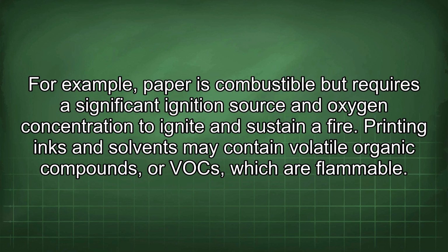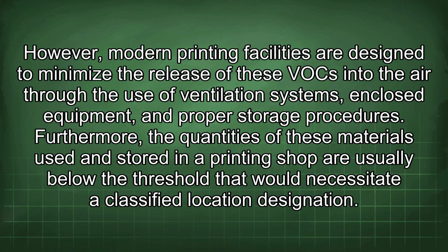Printing inks and solvents may contain volatile organic compounds, or VOCs, which are flammable. However, modern printing facilities are designed to minimize the release of these VOCs into the air through the use of ventilation systems, enclosed equipment, and proper storage procedures. Furthermore, the quantities of these materials used and stored in a printing shop are usually below the threshold that would necessitate a classified location designation.